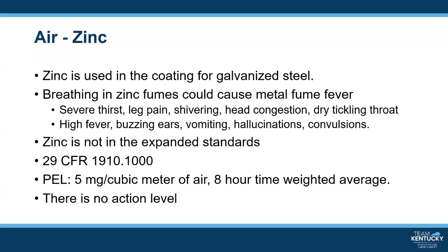If you find white dust inside your welding mask, then you may not be properly protecting yourself from the fumes. After you have finished welding, wash your hands and face thoroughly with soap and water. Do not eat, drink, or smoke within areas contaminated with welding fumes. If you think you've been exposed or if you're experiencing symptoms of metal fume fever, report it to your supervisor.